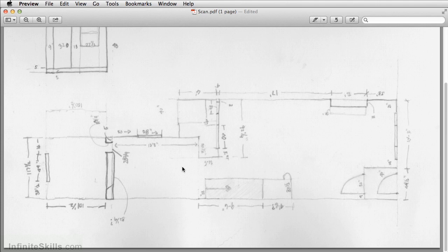I think they're 8. So to measure this, there's really a couple ways that you can do it. I'm sort of old school, so I really like to take graph paper and just measure it out to really just kind of space plan and get all the measurements of the space. Depending on how detailed you want to be, you can really get a lot of detailed and defined measurements. For the most part, I was just rounding everything to a quarter or a half an inch because I'm not too concerned about that level of detail.